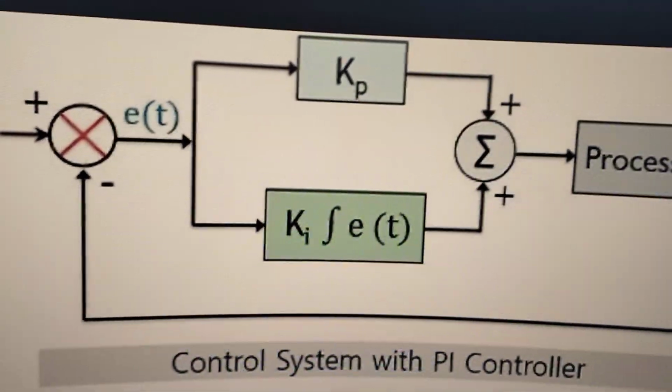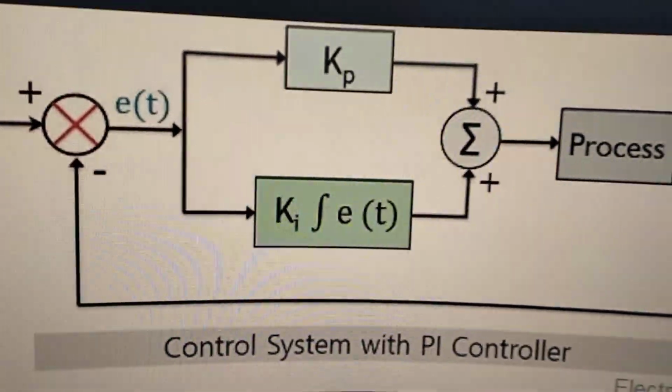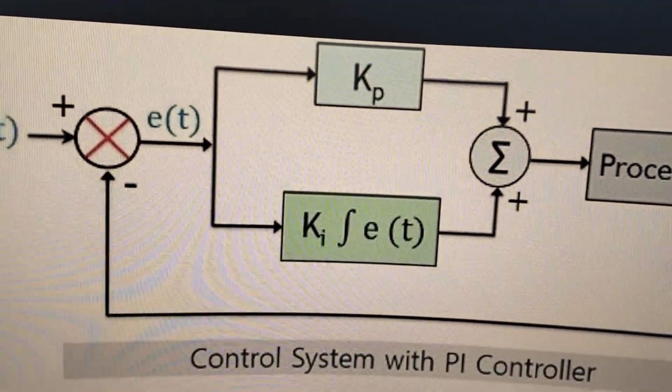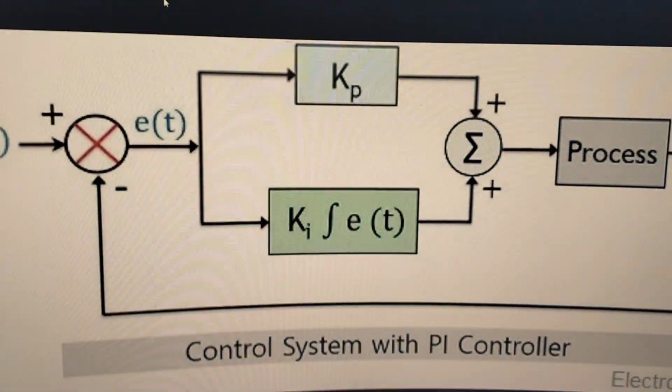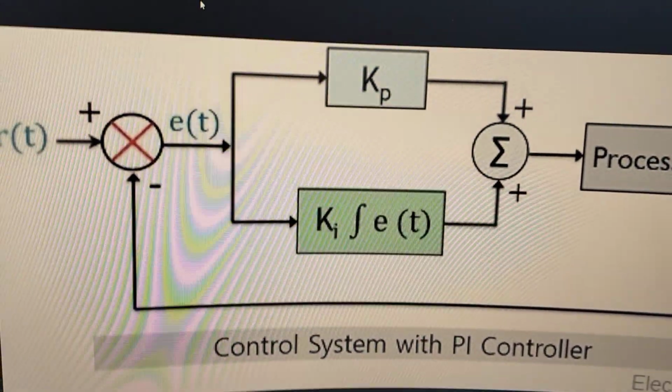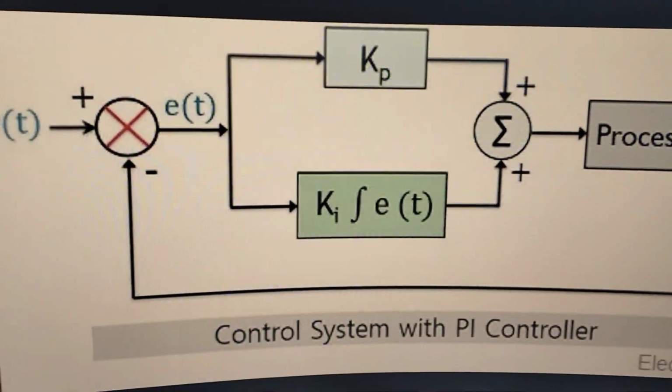It's proportional control, as it says in its name. It basically decides how fast your response is, and it responds to the current error at that point in time. So that's why it's proportional: it's proportional to your current error.